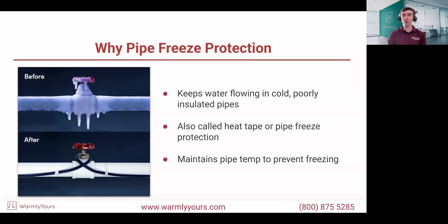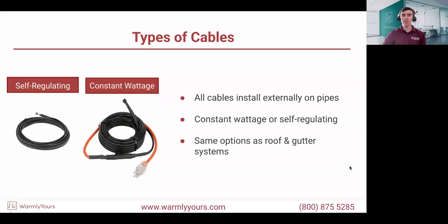Trust me, we've heard all sorts of names and words related to heat and pipe and tape, right? Heat tape, heat trace, pipe freeze. It's all the same thing for us. But this is basically maintaining the pipe temperature to prevent freezing. It doesn't have to keep it hot. It just has to keep it warm enough that there's a trickle so that the pipe doesn't expand and burst. Correct. Yeah.